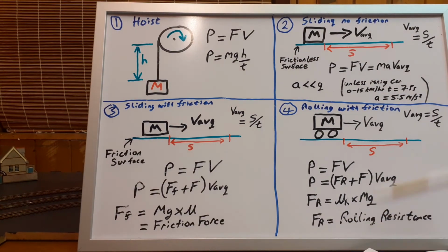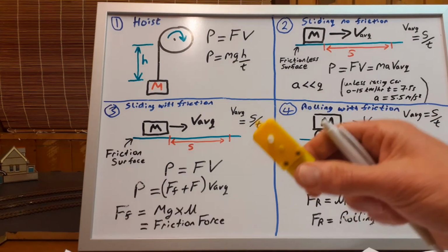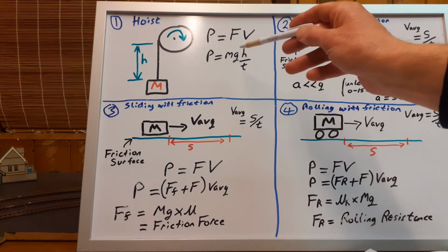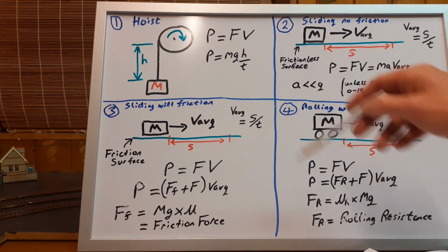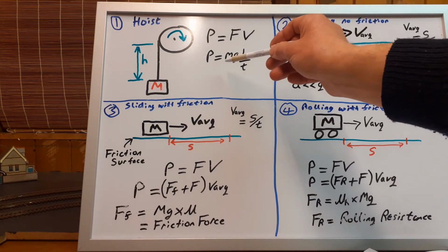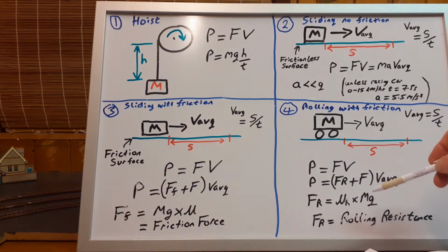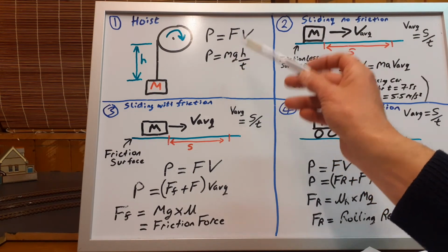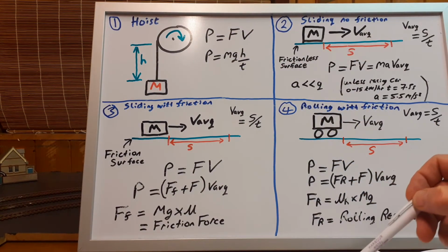So if a cheap and cheerful motor like this is only giving you 10% output of what it specs, then if you find out what the worst case scenario is, at least you want a tenth of that. So I'd nearly double the wattage. So what I'm saying is, find out the worst case scenario, double the wattage, and then find a motor with that wattage.